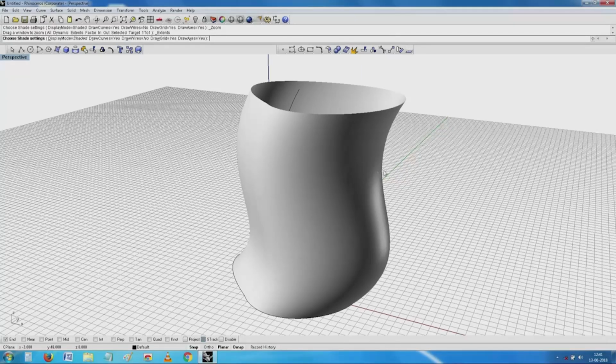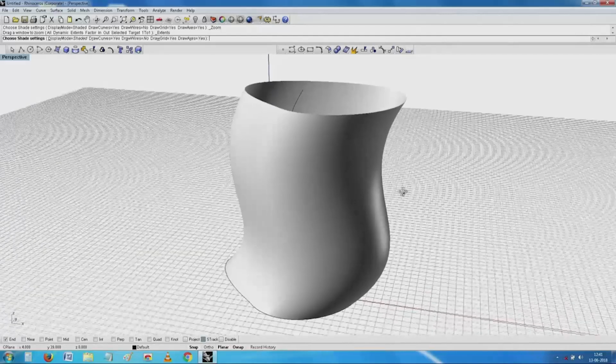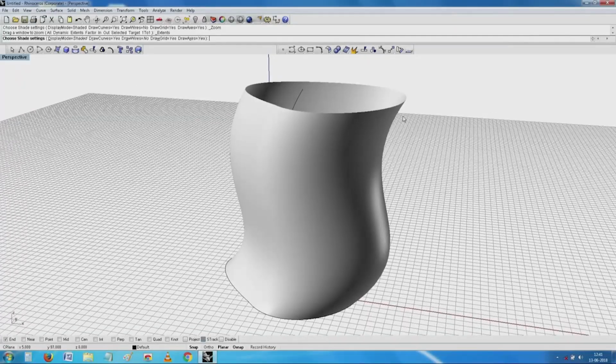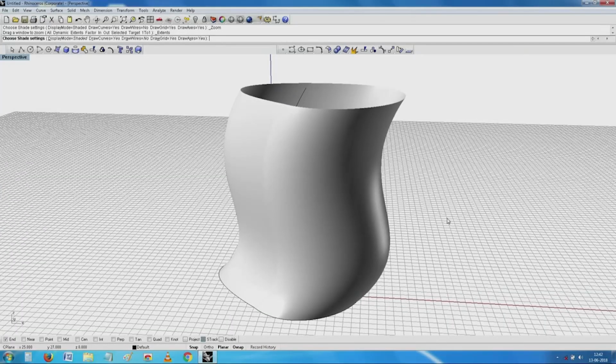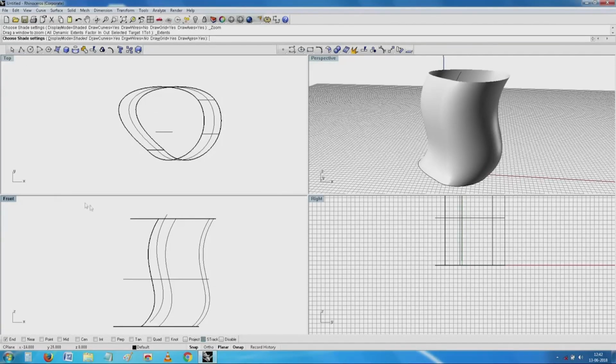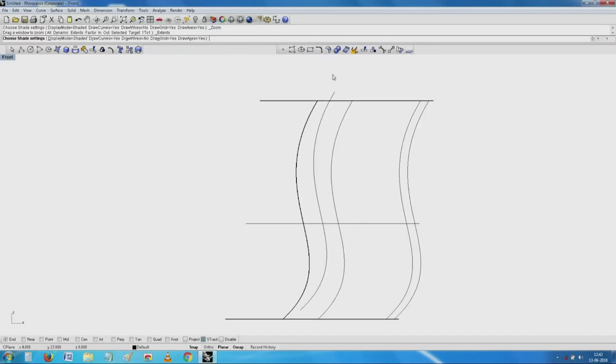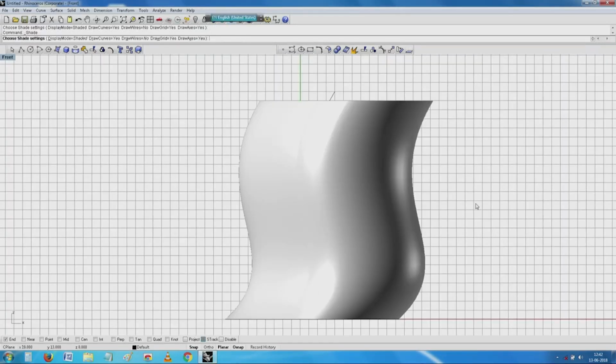One of the first things is, how do you now orient it for printing? In principle there is no problem. However, if you are trying to make shell components like this, the disadvantage is that making it thin is a problem. So you end up with a definite thickness of at least say 1.5 or 2 millimeters and a huge amount of support material. Our problem is the support material. Do you go ahead and spend so much effort and time on this? That is our issue with the support problem.